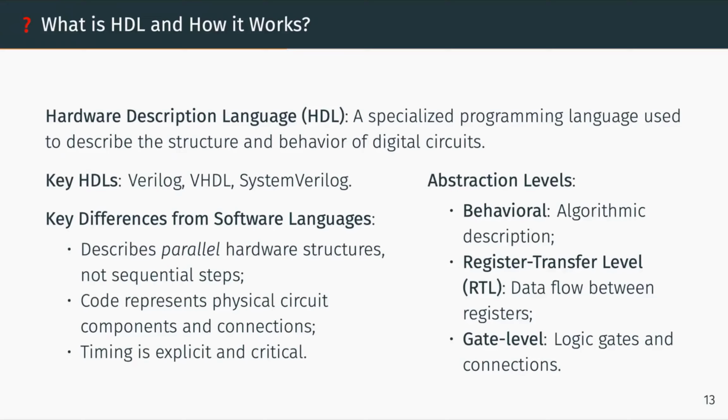That's the simple way. We can also use the register transfer level, that's the RTL, where we want to see how data flows between the registers. That's more explicit than the behavioral model. For the behavioral model, we rely on the compiler to transform that into RTL.